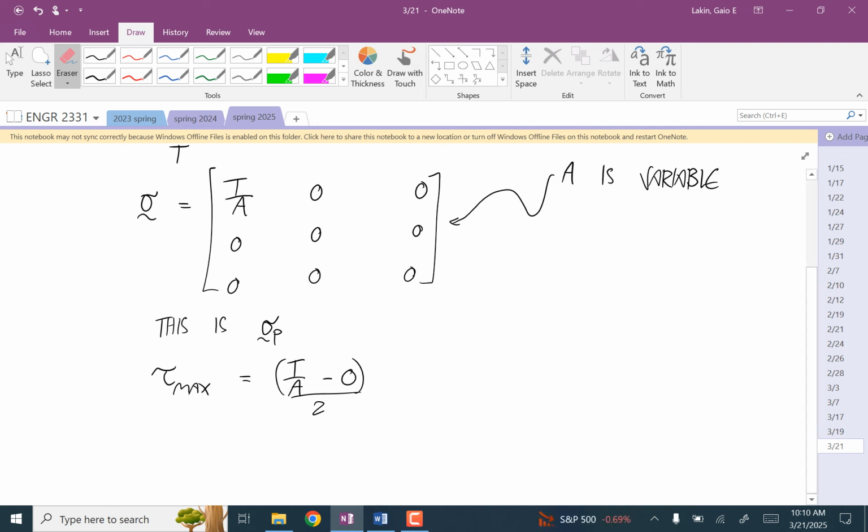So I have to be pretty specific about what point you're doing. If there's only stress due to tension compression, then I don't have to be specific about anything on the cross section. It's all the same. If there's stress due to bending moment, I have to tell you the height on the cross section. Shear force, I have to tell you the height. And then torsion, I have to tell you exactly where on the cross section.